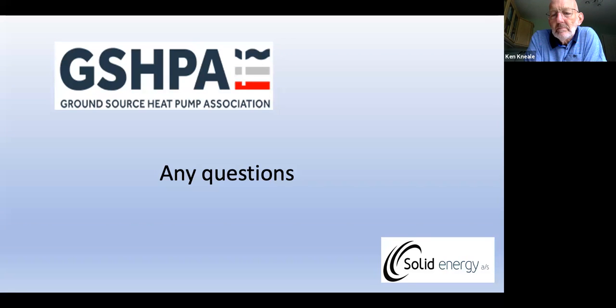I just wanted to make a point actually. When you started out there, Ken, most of the heat pumps that I tend to work with, I've actually been told in the past that physics means that you cannot increase the delta T between flow and return of more than 10K. And usually it's more like 7K on a heat pump, which then means that putting them into district heat schemes is quite difficult. Now, I don't hold with that 10K always, but the solid energy heat pumps certainly enable that wider delta T, which means that you can quite easily slot them into district heat schemes and be compliant with the code of practice for district heat schemes.